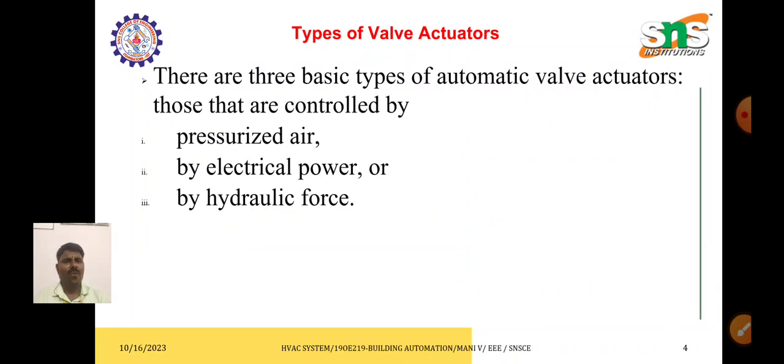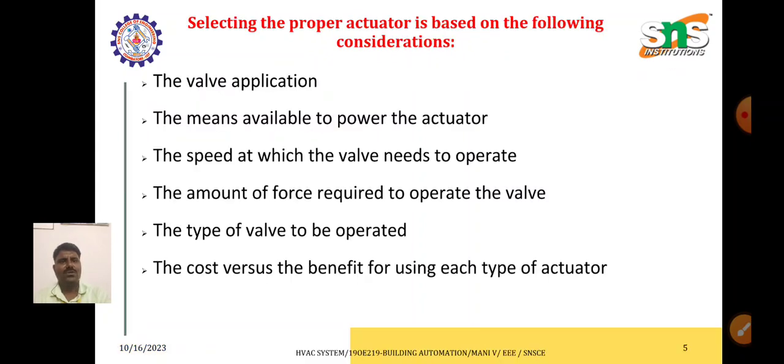The types of valve actuators use pressurized air, or electrical power, or it may be a hydraulic force. So the selection of the proper actuator is based on the following criteria. One is the valve application, where we are using the valve, and number two, the means available to power the actuator,